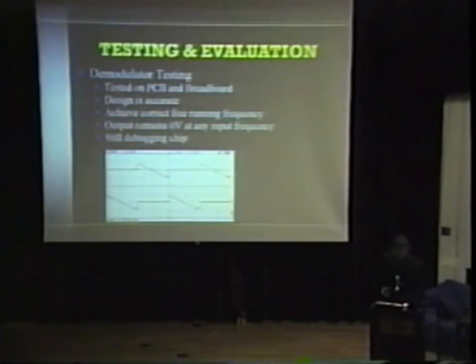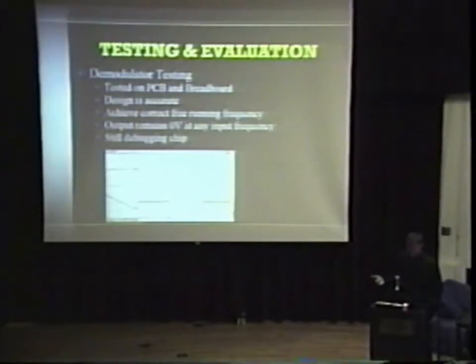In demodulator testing, it was tested both on the printed circuit board and the breadboard. The design was reviewed several times and it was accurate. I achieved the correct free running frequency of 199.4 kilohertz. The problem was that the output remained 0 for any input frequency, and I'm still debugging that chip.